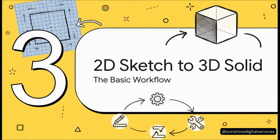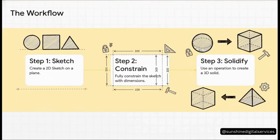Okay, that's the philosophy, but how do you actually make something? It might seem intimidating at first, but honestly, the basic workflow in FreeCAD is super logical. It really just comes down to a few key steps. And here they are. Step 1, you start by drawing a simple, flat, 2D shape. In FreeCAD, this is called a sketch. Step 2, you lock in all its dimensions and rules. This is super important, and it's called constraining the sketch. Then, once your sketch is perfectly defined, you move to step 3. You use a special operation, like an extrusion, to pull that flat 2D shape into a 3-dimensional object. That's it. Sketch, constrain, create.